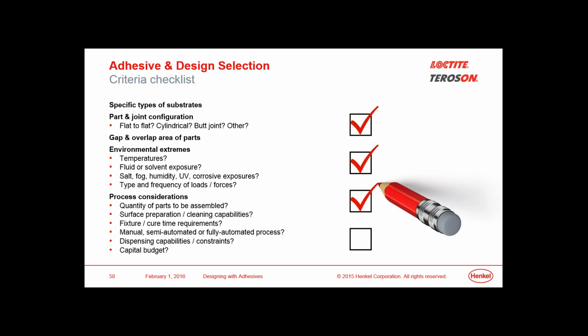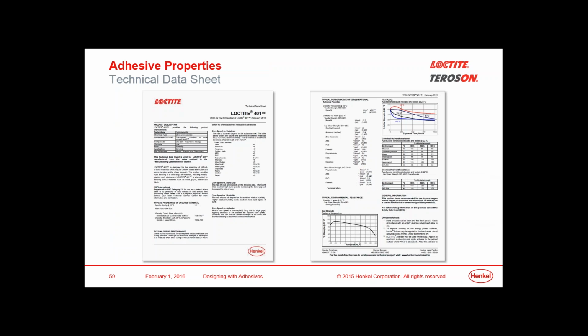The package size is going to define how long that package size will be in process or being used in production. It also tells you what type of flow rate you need to achieve for your application itself. So the package size is a major consideration for deciding what is process compatible. Here's an example of one of our most popular instant adhesives, cyanoacrylate LOCTITE 401. LOCTITE 401 is a water-thin viscosity, very fast fixturing cyanoacrylate adhesive, which again sticks to virtually anything except glass.